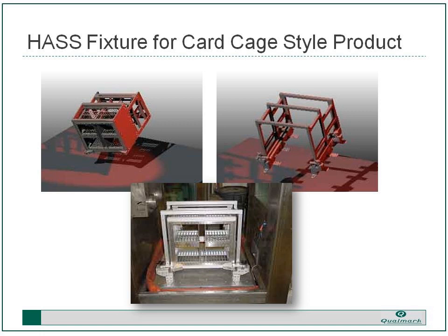When you get into a situation like that, one of the best ways to approach it is to design a fixture that is built to hold those assemblies just like they would be held in a product, except it's all a vibration fixture designed to transmit the vibration in well. So you're not actually testing the final product. You're testing all the boards that go into the final product and all the interconnects that go into the final product. But then when it comes out of HASS, you remove all the boards from the fixture and screw them into the unit.